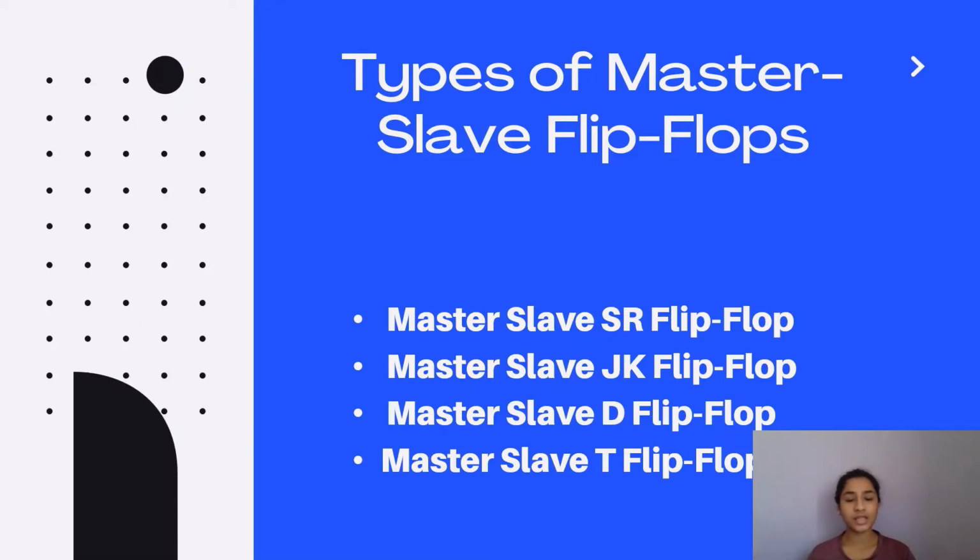Now, master slave SR and T will work almost similar to the normal working of master slaves. If we know the truth table of SR, JK, D and T, one thing we must remember is that it will follow its truth table as long as the clock input is 1. But when the clock input given to it is 0, it will have no effect on the master, which means that the output coming out of the slave will be retaining its previous state.